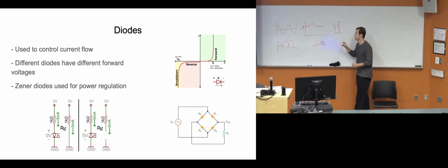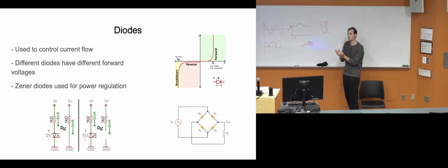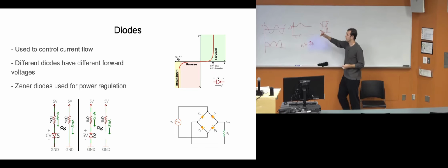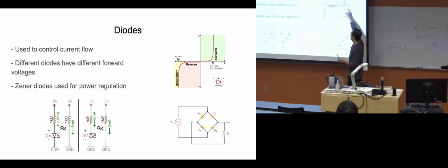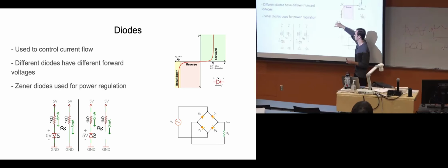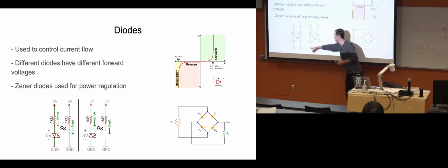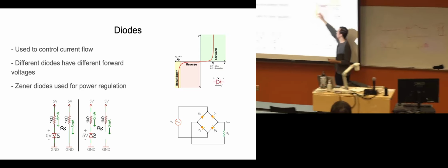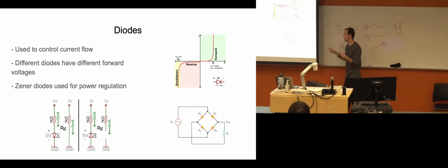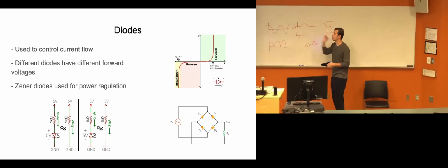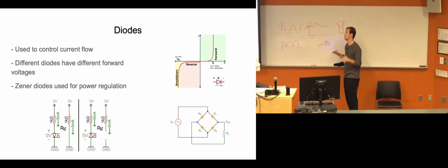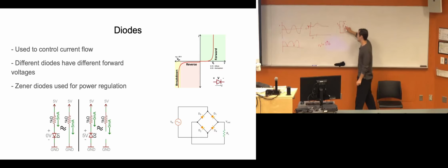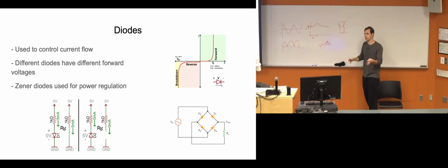Zener diodes are special because, I'm not going to pretend to know the physics, but they can change the breakdown voltage of a diode. So the breakdown voltage is when you get such a big reverse voltage on it, where it's basically a negative voltage across here, right? A super big positive voltage on the wrong side of the diode. It actually breaks down and conducts current. Okay, so it breaks the diode. Normally those are really big for like LEDs and stuff. You would have to put a huge voltage on them to be able to do that. These are specifically made to have known breakdown voltages, okay?